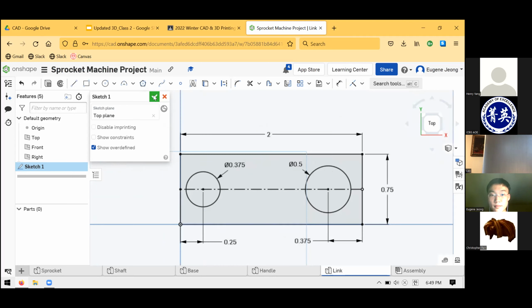My circles are not black. So make sure their size is dimensioned, make sure their position is fully defined. You'll probably need a dimension to do that. And make sure they're fully related to the construction line, which itself should be black because it's fully related to this rectangle.